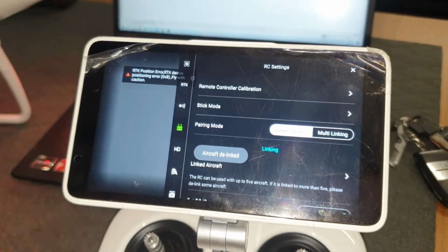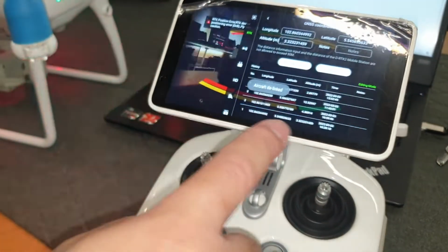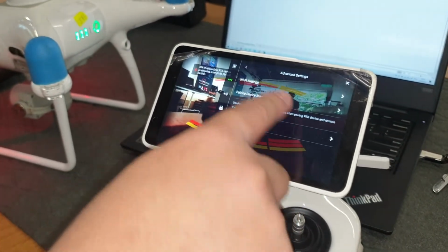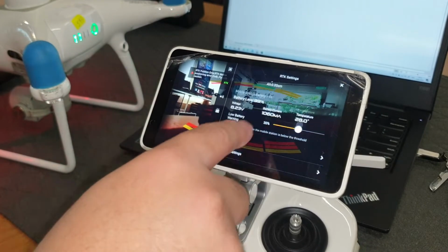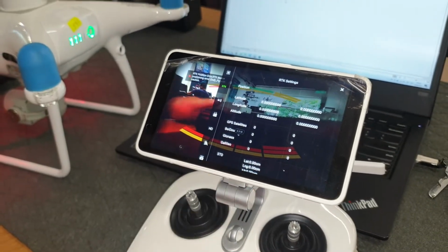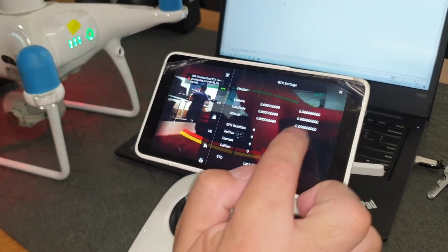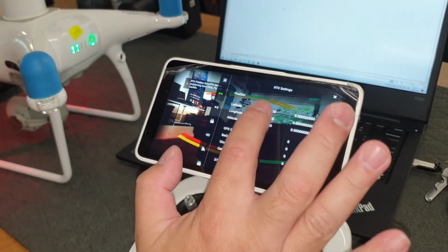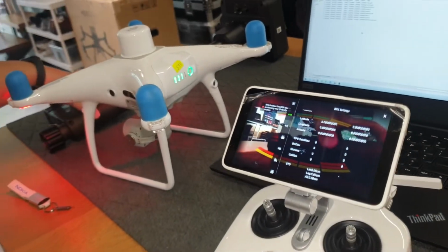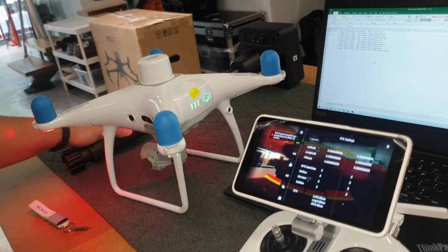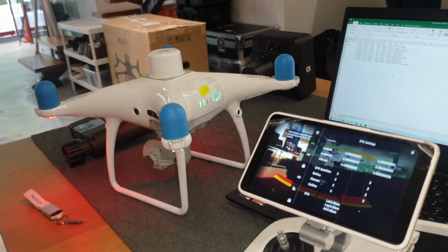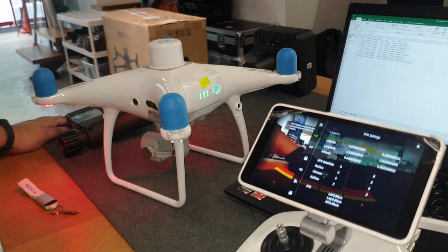That's quick. So now what's happening is, link failed. So you have the aircraft with an error, and also it's all 0. So you will have the base station at the coordinates that you place. Aircraft out there, it's going to link the two, and then the RTK fix is between the rover and the base. The drone, which is the rover, and the stick, which is the base. So you can then have RTK connection all the time while you're flying.